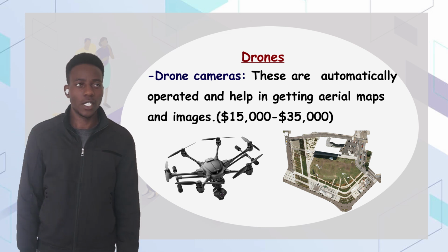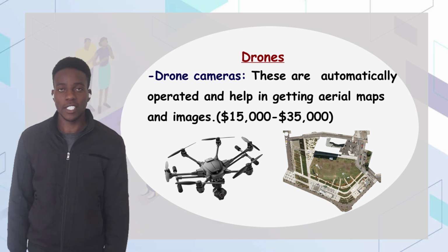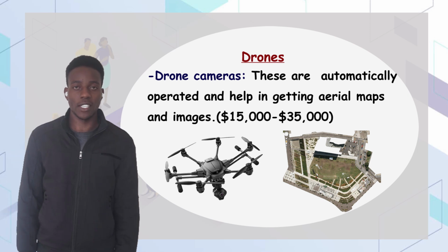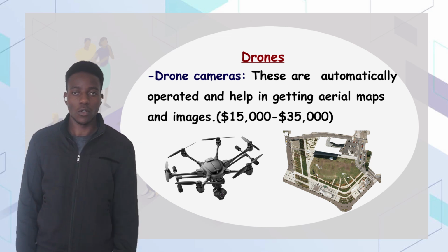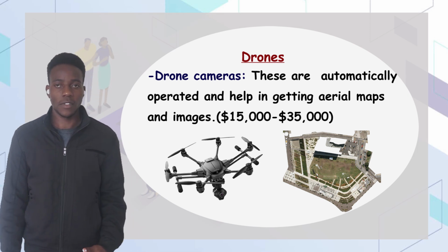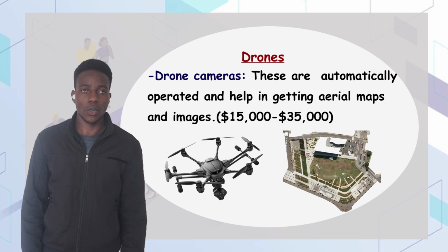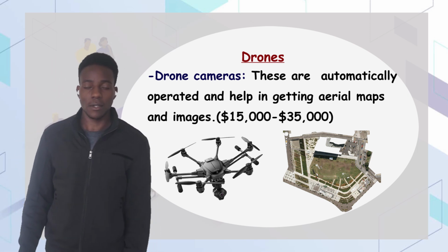Drones capture live imagery and LiDAR data to produce 3D models and topographic maps. LiDAR data, which is light detection and ranging data, is collected by mounting sensors on the aircraft which detect reflected pulsed laser beams. The cost of drones ranges between 15,000 US dollars and about 35,000, depending on the specifications and purpose.